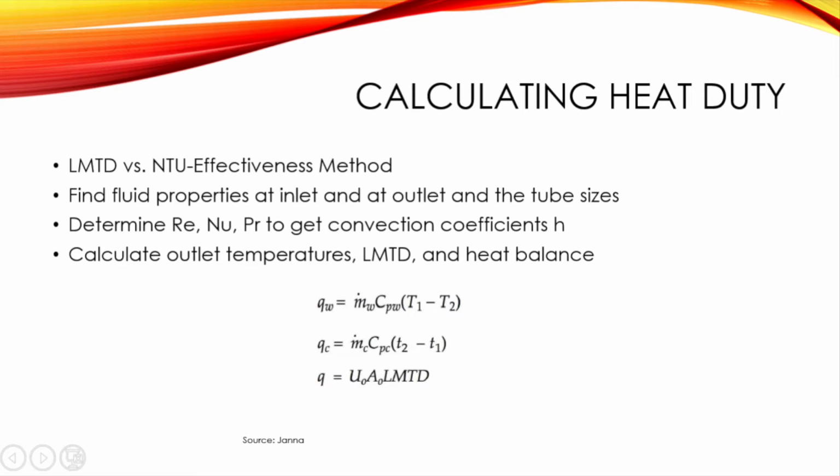With that information, we can calculate outlet temperatures or inlet temperatures, the log mean temperature difference, and the heat balance of the warmer side, the cooler side, and the overall heat transfer. Ideally, they should all be the same, but we do not live in an ideal world.